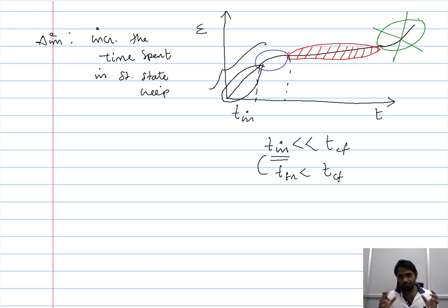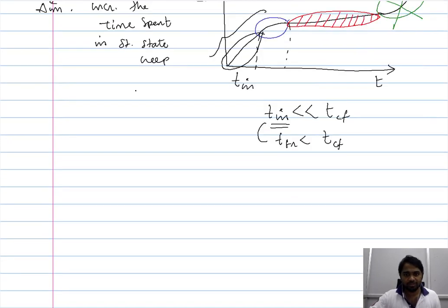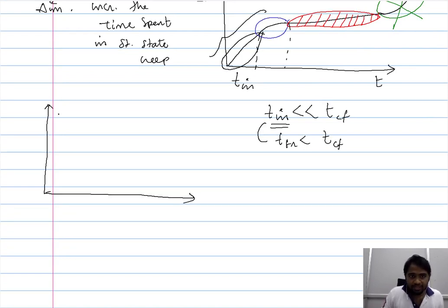So even though, holistically, when we talk in terms of the application, we say that we want to increase the life of the material, what we essentially mean is we want to prolong the duration of the steady state creep. Now, even though we refer to the steady state creep as a region wherein the strain rate is very low, close to zero, there is some amount of strain associated with it. Even though we characterize the steady state creep as a region of minimal strain, we cannot say there is zero strain. There is of course some minimal strain.